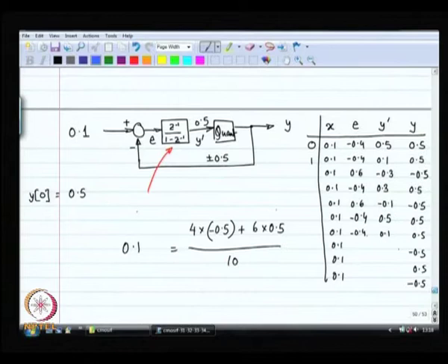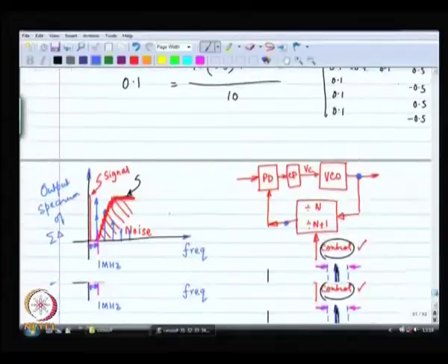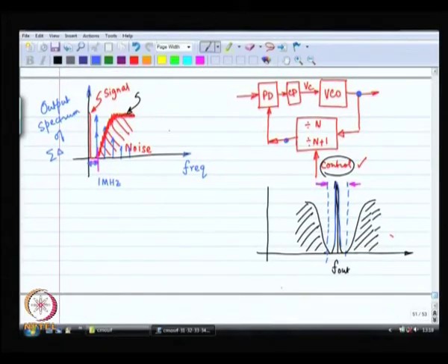Then I briefly discussed the sigma delta modulator itself, we looked at the dynamics, we saw that a first order sigma delta is still going to be periodic, which is bad news, we have to make higher order modulators. Then we saw that suppose I make a higher order modulator without paying too much attention, then I am going to have phase noise problems anyway. Okay. So, you have to design the sigma delta modulator carefully enough, so that you do not pollute your voltage controlled oscillator output.